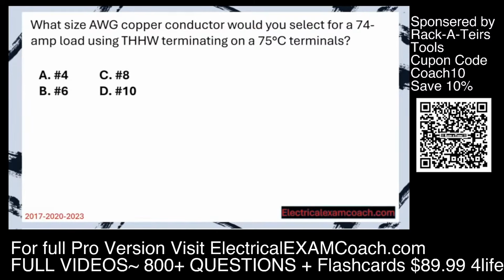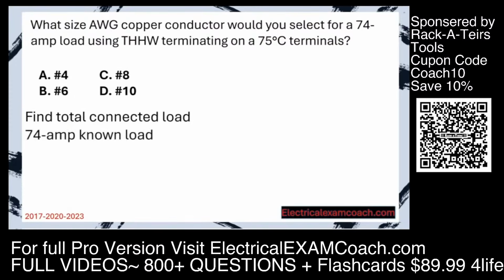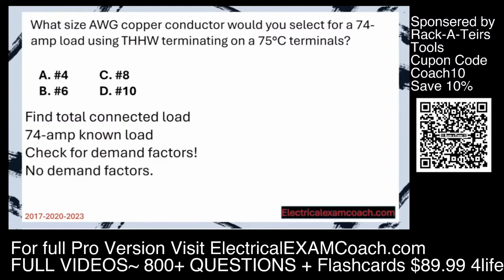What size AWG copper conductor would you select for a 74 amp load using THHW terminating on 75°C terminals? Step 1, find the total connected load. It's 74 amps. Now, let's check for demand factors. Well, in this case, there's no specific pieces of equipment and there's no continuous load, so there are no demand factors. And we have to remember that our wire must meet or exceed the known load.